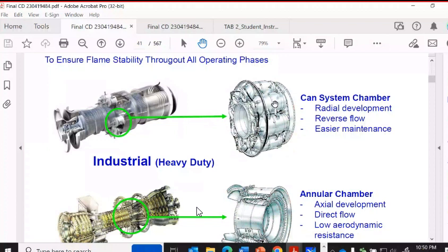You got to remember, airflow is moving in a spiral direction. It's circulating around the turbine as it's passing through, so it's making a circular motion. And so if one or even more of my chambers are giving me a problem, my temperature across here can drop significantly. As this mixes together coming out this side of my turbine, my temperature pattern is going to be altered. It's not going to be real stable through here.